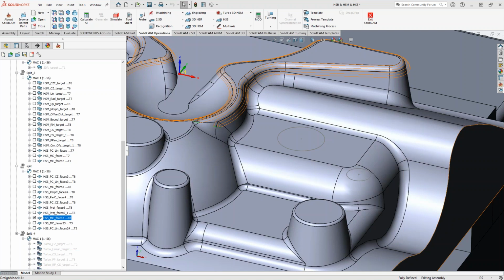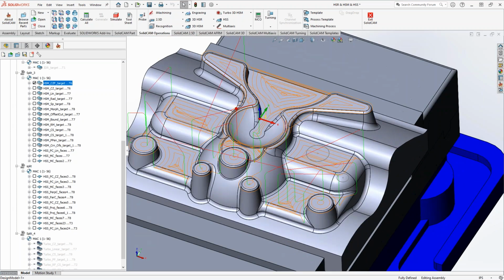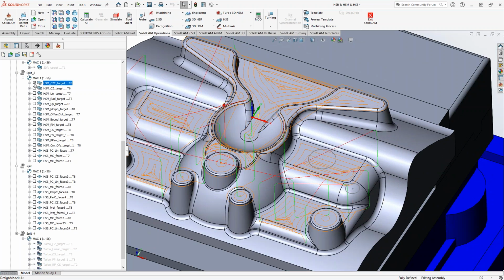Yeah, that's a good way to put it, because you notice that with the surface-based toolpath, you get that really fine detail, whereas with the HSM, like Kevin said, you're basically applying one technology to the whole solid. So that's what we need those constraint boundaries for, because that also gives the ability to limit the travel of the tool and break up your solid into the different technologies that you'd like to do. Like we saw the other day with the HSM boundaries, some of these toolpaths make sense to be done on certain areas, but maybe not the whole part.